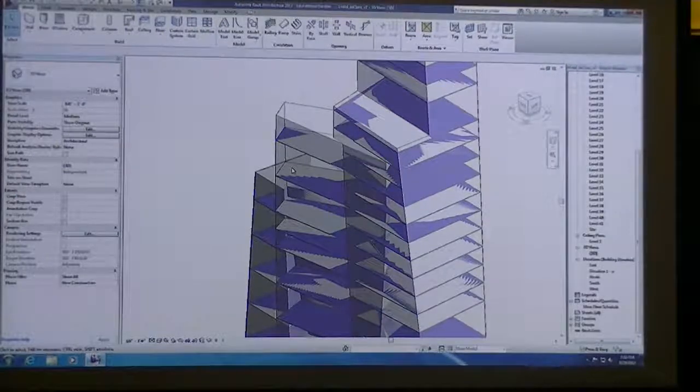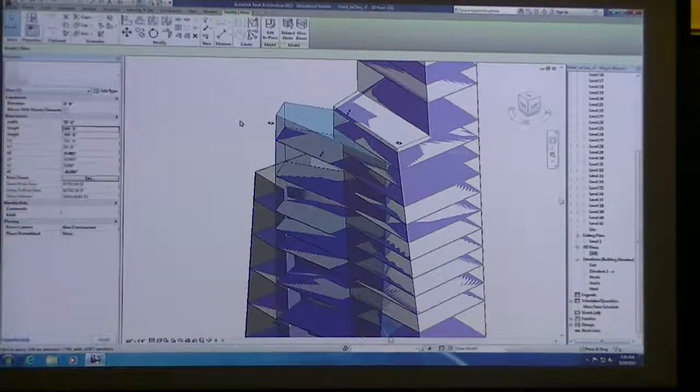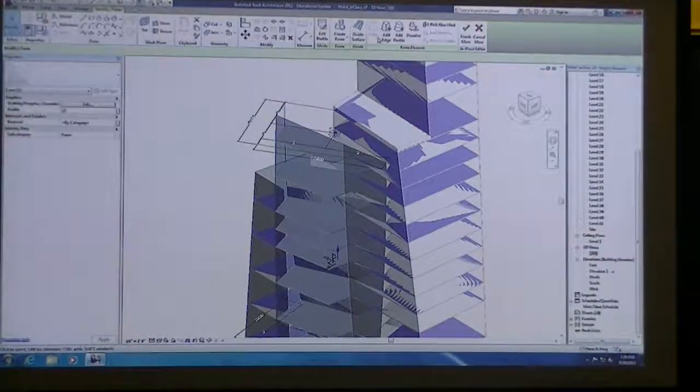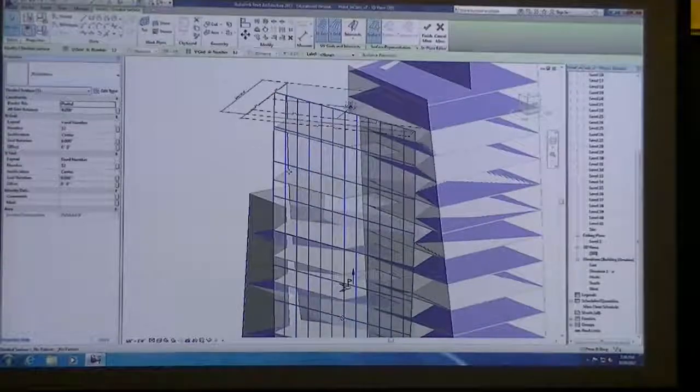One would be to go under massing and site, and when we click on our mass, edit in place that particular mass. Once we do that, we get our familiar options again to divide the surface. So I could divide this surface up. We all know how to do this, I'm not going to go into it, but you can then make a curtain panel pattern-based system like you did for your bridge.